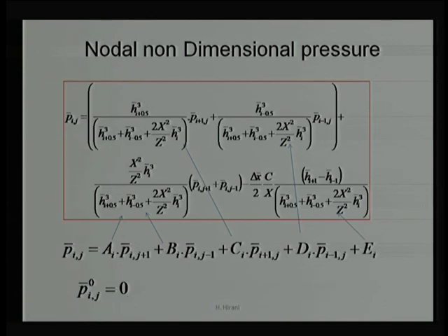However, sometimes we evaluate the pressure profile using some common approach like a hybrid approach. We find out the pressure profile using the hybrid approach and evaluate all the nodal pressures, assuming that will give accurate results, and then we start doing iteration. That kind of approach is always helpful, because instead of starting from 0, we are starting with some definite value and coming very close to the actual values.